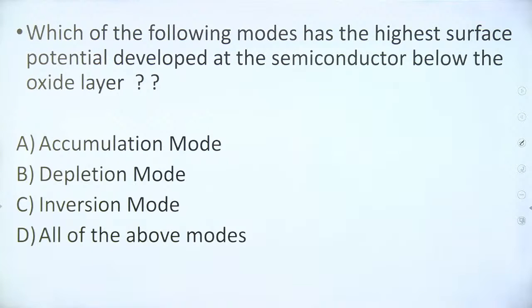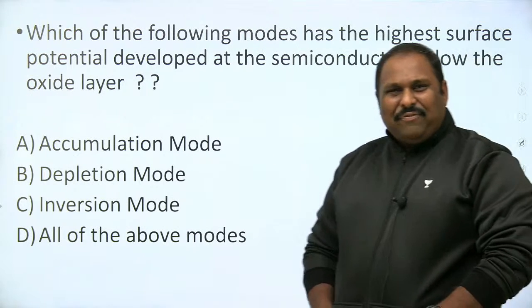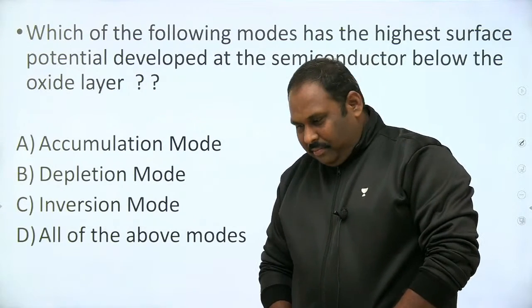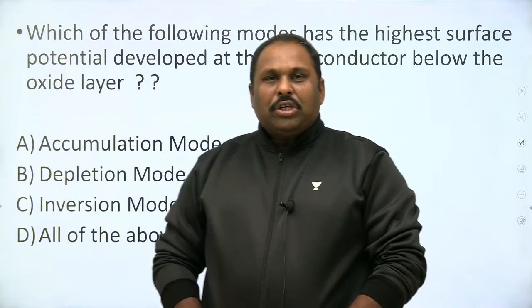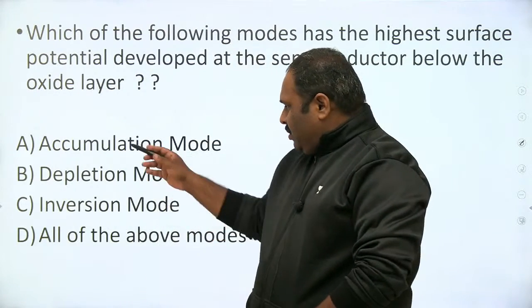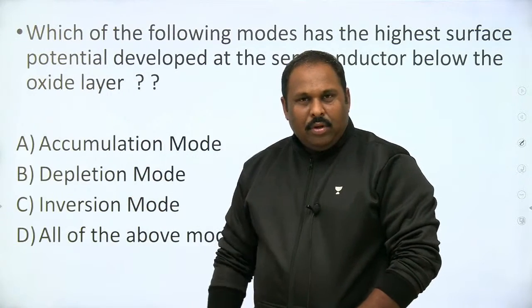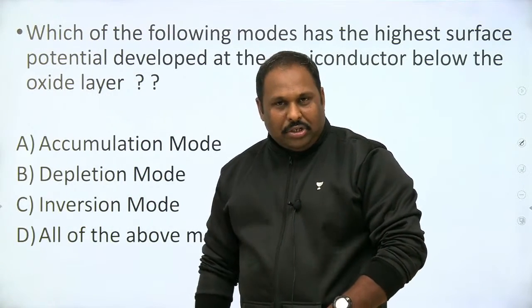Inversion, inversion, inversion. All of you are very clear with the word inversion. Absolutely. So what makes this new word, surface potential, come into the picture? Why is it not in accumulation mode or depletion mode? What makes inversion mode very interesting?